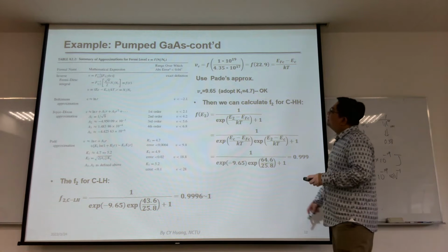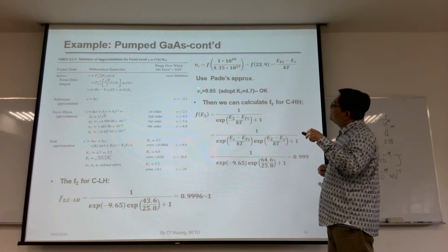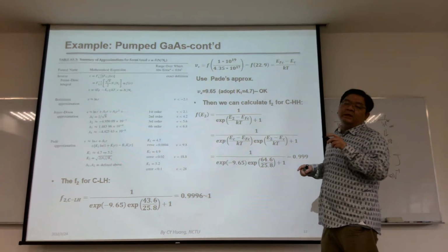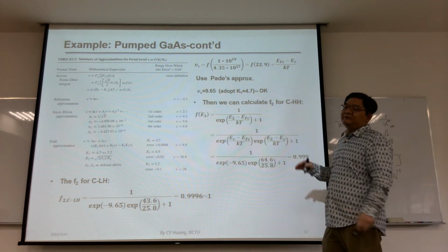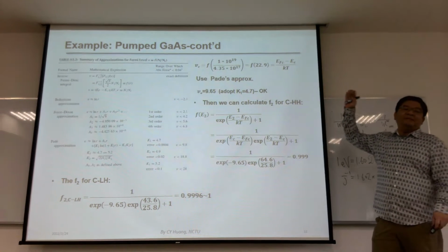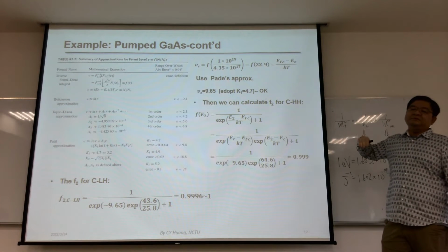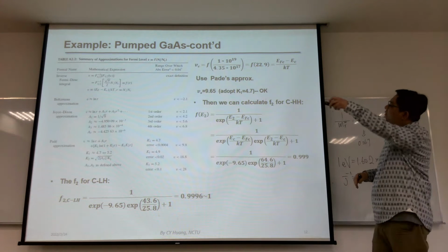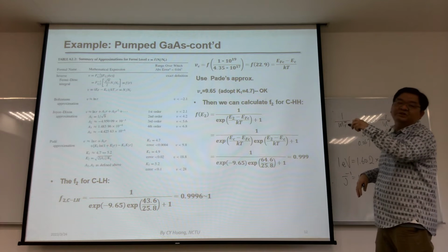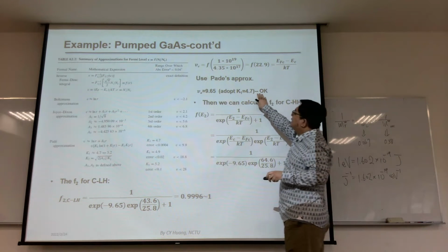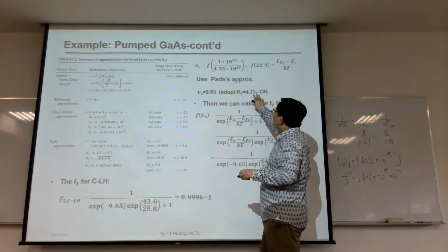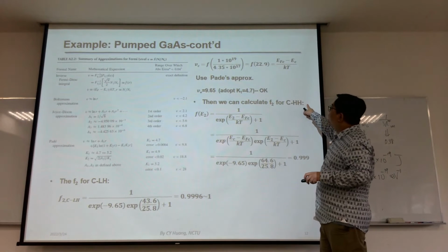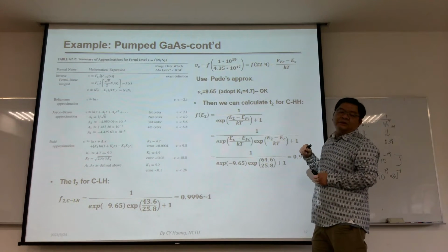Okay, so with the 1e19 carrier density, you can evaluate the position of the Fermi level for each case. The whole procedure is just the same. For the first one, we need to do the Boltzmann approximation, and the eta is 4.7. Then we know the position of the quasi-Fermi level EFC.